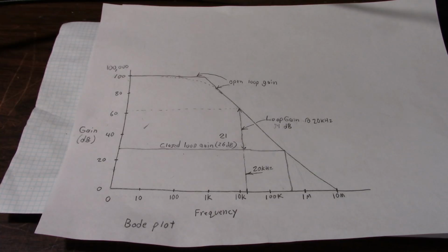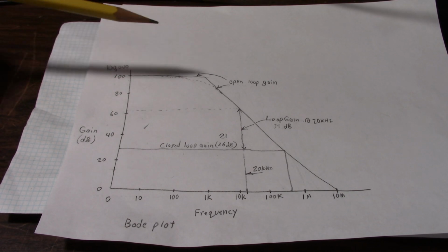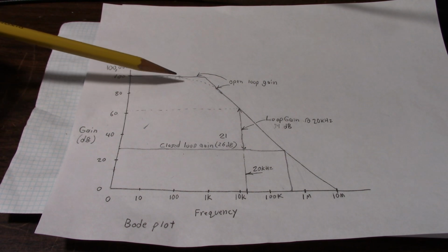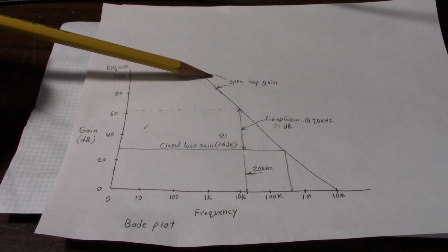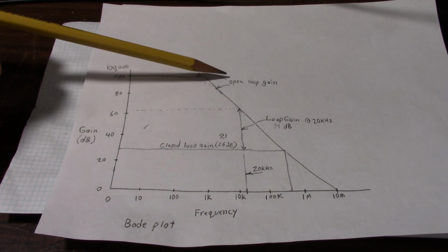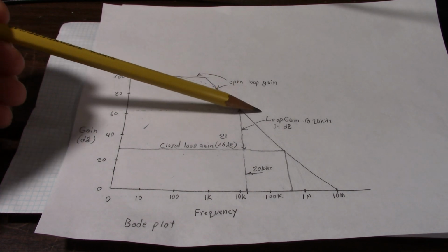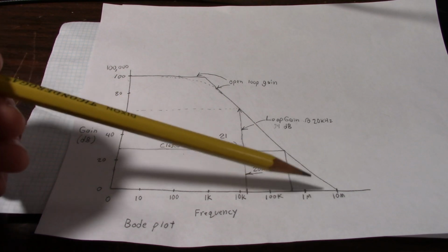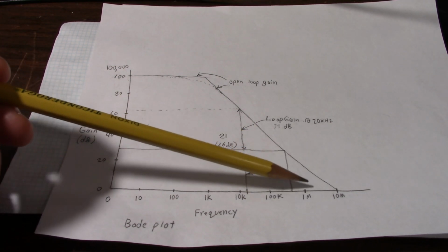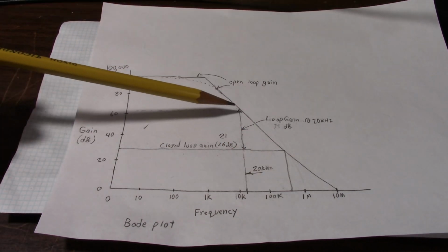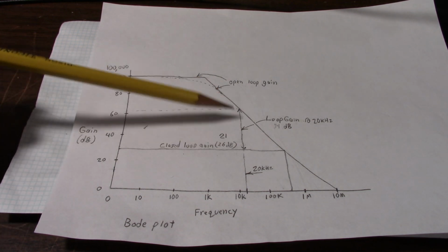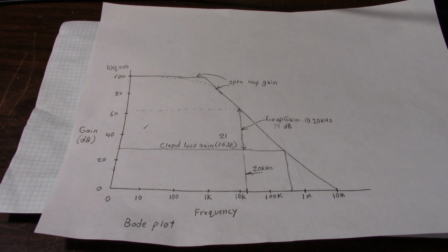Now I'll give passing mention to more advanced compensation schemes. Those schemes give you a faster roll-off. That way your open loop frequency will stay much higher, longer, but it'll roll off faster so you don't run into phase issues or phase margin issues at higher frequencies. So at 20 kilohertz, negative feedback has more loop gain available to linearize the amplifier.